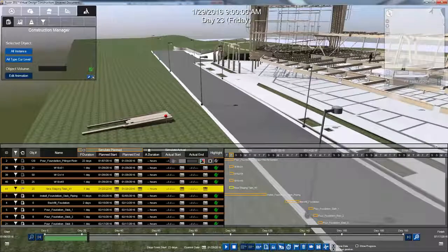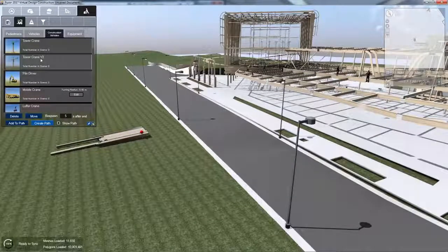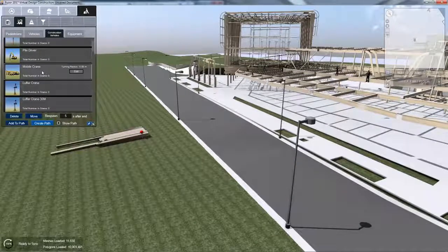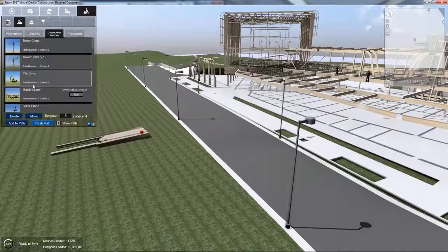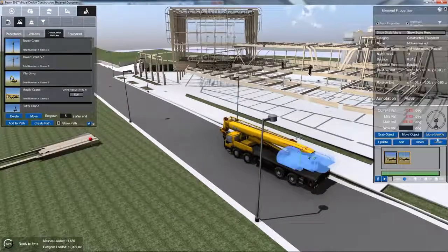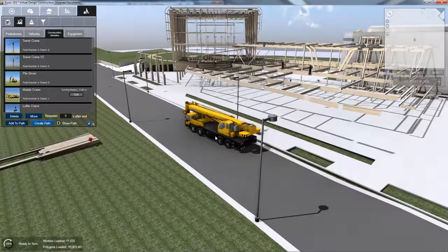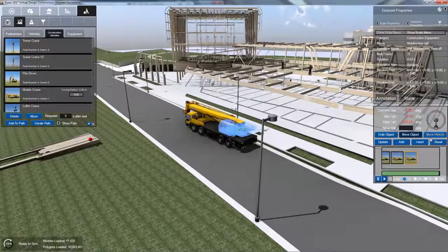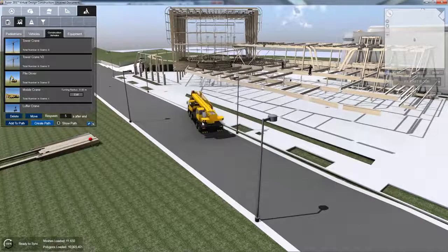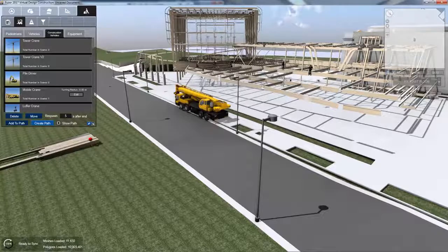Where that comes into effect is Fuzor also gives you a full array of construction vehicles. So let's say if, for instance, I have one of my cranes come in, I have a mobile crane in here. What I can do is I can quickly animate that mobile crane to, say, if I go over here, say, add another keyframe, and it's just keyframe animating. So I'm adding one in here. Let's add another one over here. Let's hold shift and rotate them around a little bit. Add another one over here. Going to shift him into place.